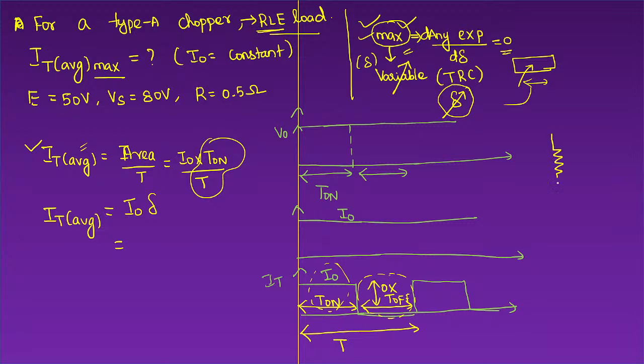Even in rectifier circuits I clearly told that whenever inductance is given and we receive a DC supply at the output side, the inductor behaves as a short circuit. So the voltage drop across the inductor will be 0. You don't need to consider that effect.